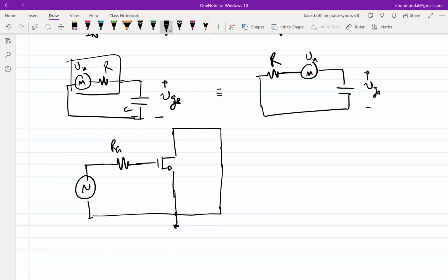So when I'm doing signal analysis, I'm not taking noise into account, right? So this is signal analysis now. This is VI. So what will be the signal current? GMVI. So what is the power contained in this? Again, when I say power contained in this, don't look for a resistor, simply square it. I'm talking about mean squared, right?